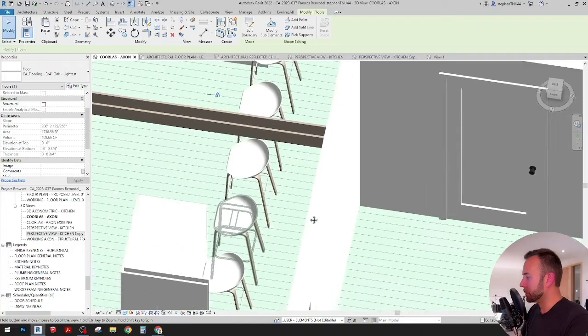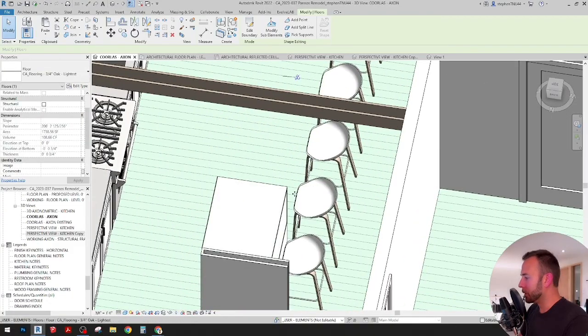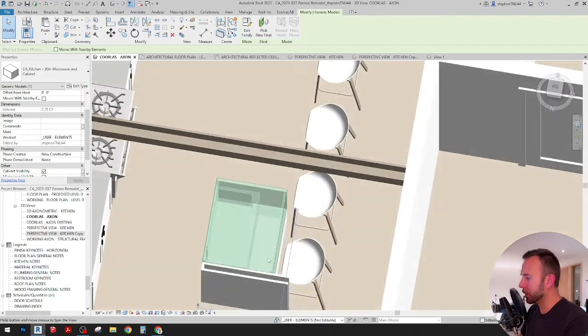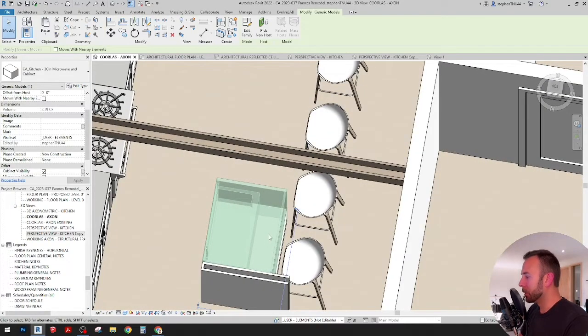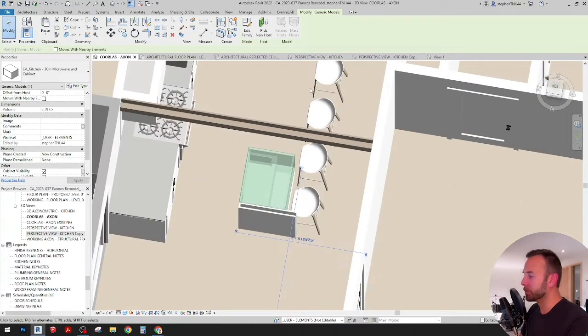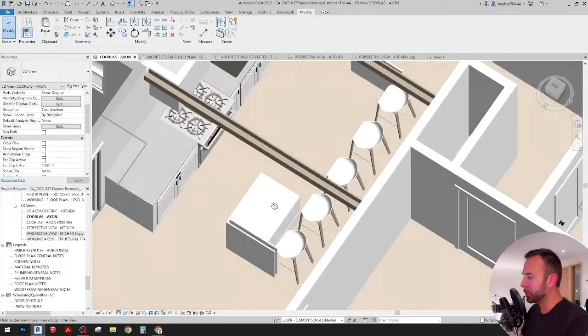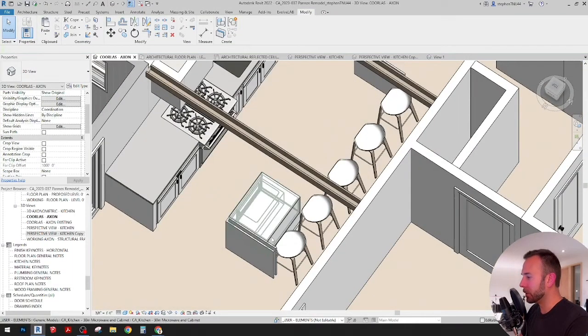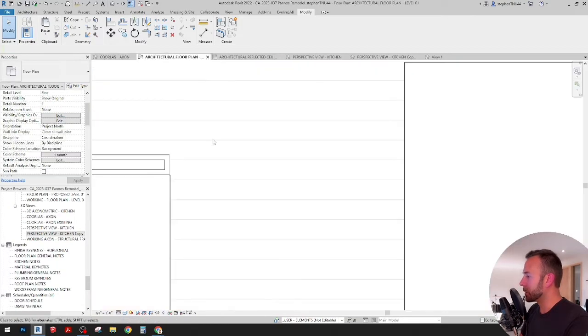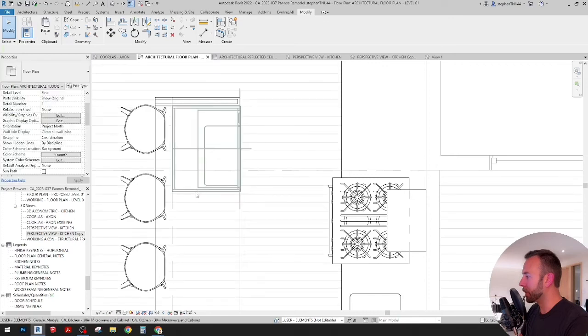And with the microwave depth, it's typically shallow enough that, if I highlight it here, you can see we can get an outlet on the top surface of the interior, so we don't have to build out a full utility wall to host outlets, things of that nature. And we can just put a backing panel on these 24-inch depth cabinets. So that's how you would handle that.